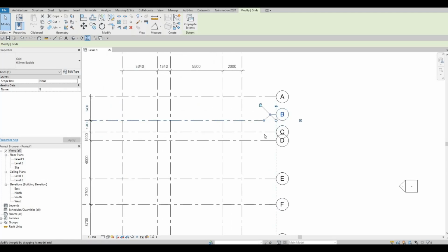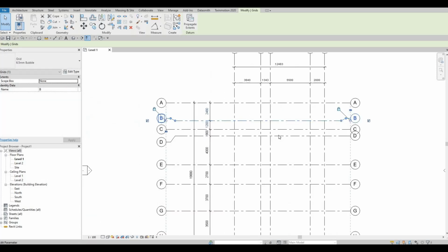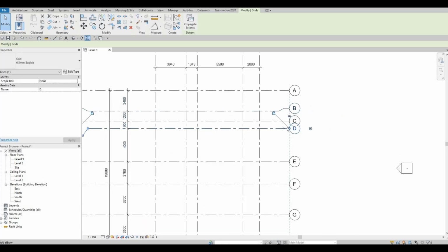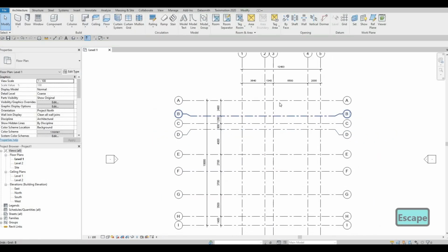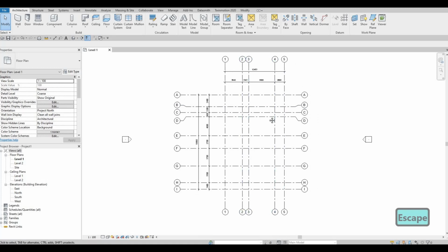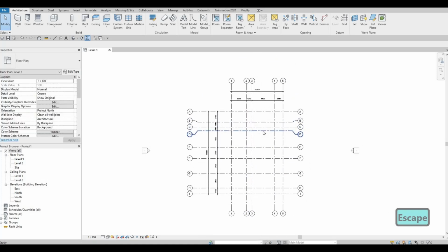So here I'm gonna add an elbow again and make sure everything is aligned from the left side. This one as well, and usually it will show you that there's an align. As you can see, that's a temporary dash line, and everything looks much better and everything is organized. So now everything is done.